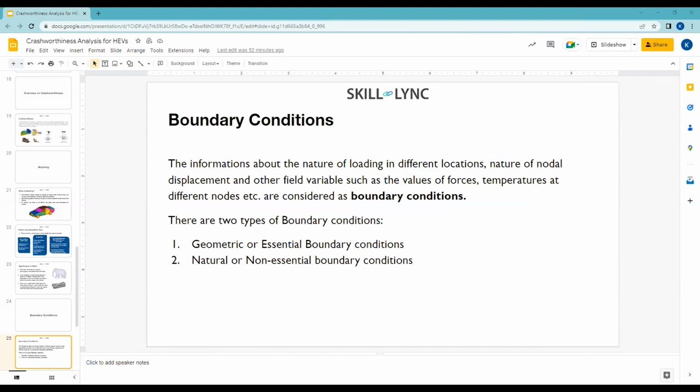So over here, suppose you apply a load of say 10 Newton. What are the constraints to this particular cantilever? There are two constraints. One is this fixed support Fs, and another is your force, which you are applying. Now with respect to which of them can you call it a cantilever? If force is not there, if one side is fixed and one side is free, again you can call it a cantilever, right? That is the important thing, without which your geometry will not exist as a cantilever in itself. So this becomes your essential boundary condition and this becomes your non-essential boundary condition.